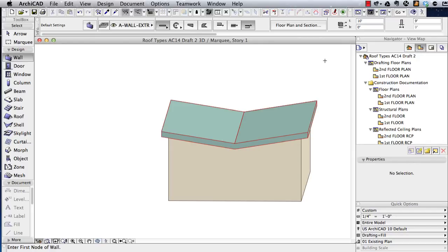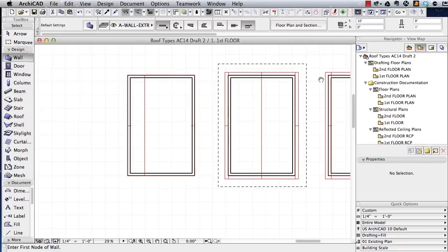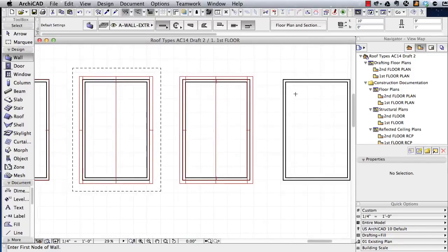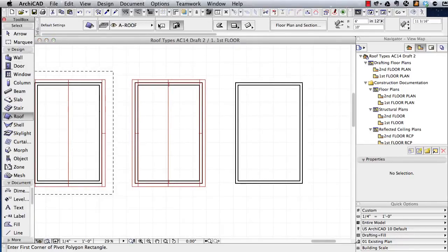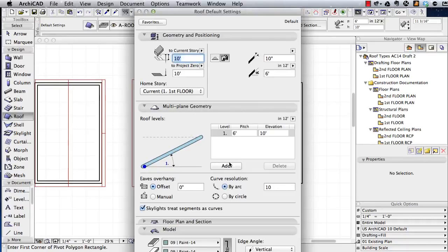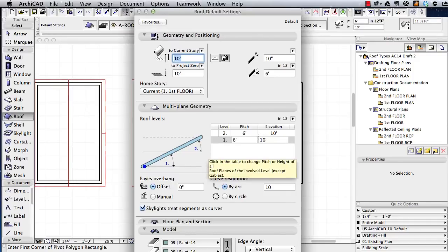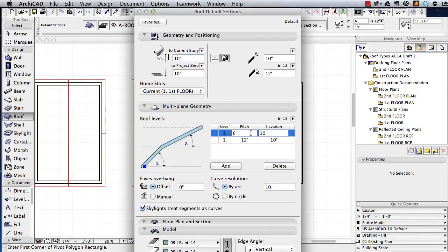Now moving on, we're going to go on to the M-shaped roof, where we have a similar issue where we need to create a downward slope. There are different ways to do that, but certainly one way would be to have a negative sloped roof. So we could do something similar to what we had here, except make this have another plane, because we want to make this perhaps 12 and 12, and I'll just take this some distance over.